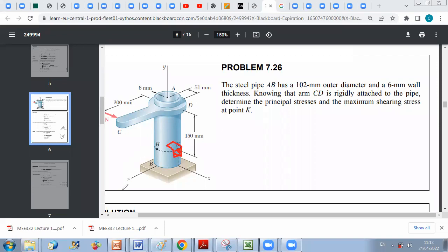And we'll see together how we can deduce 3D stresses once we know the 2D stress at one location, because when you change orientations, the state of stress will be different, and you can move from 2D stress to 3D stress in other elements. So we always try to select the elements easier to work with to get the state of stress in a certain frame. Once we get it in this frame, you can deduce in other frames, x prime, y prime, z prime, what the state of stress will be.